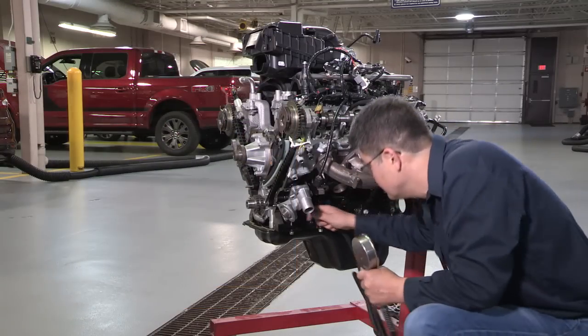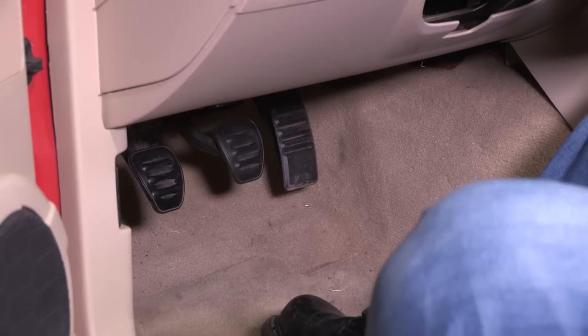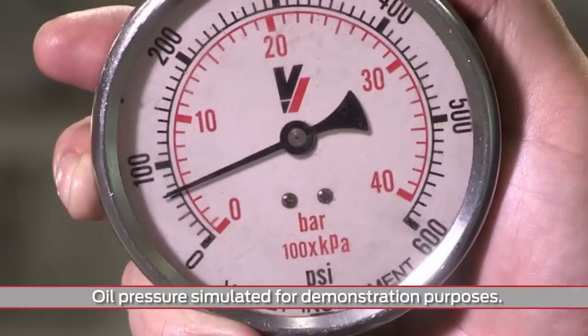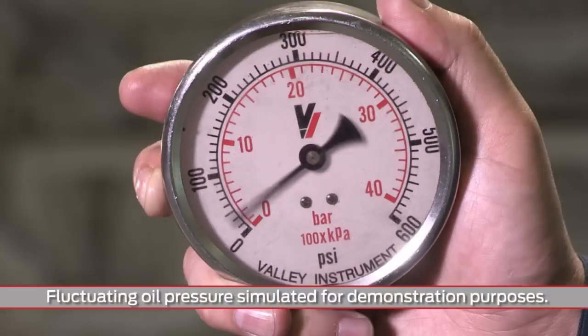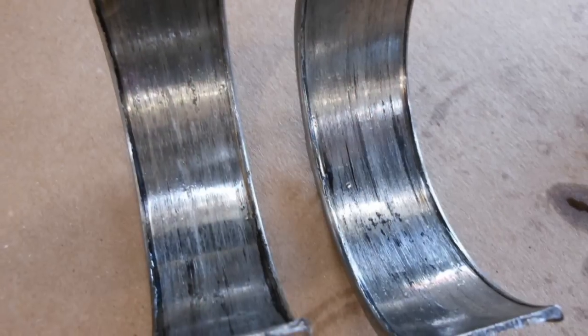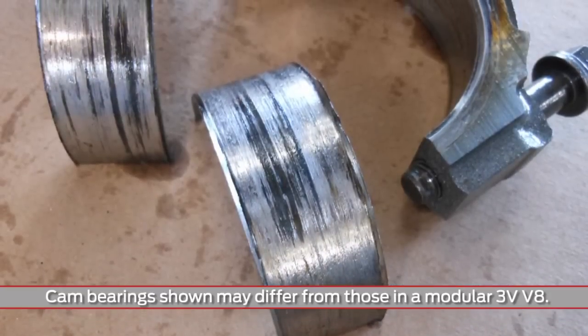Install a mechanical oil pressure gauge at the oil pressure sensor. Start the vehicle, but do not step on the accelerator. Monitor the oil pressure while the engine oil is cold and during the engine warm-up cycle. Look for fluctuating oil pressure when the engine becomes hot. That suggests an excessive oil bleed-off condition, such as a failed bearing.